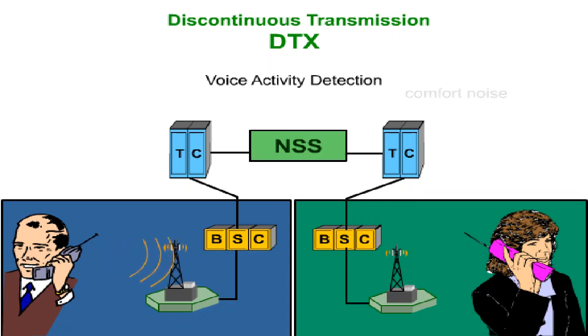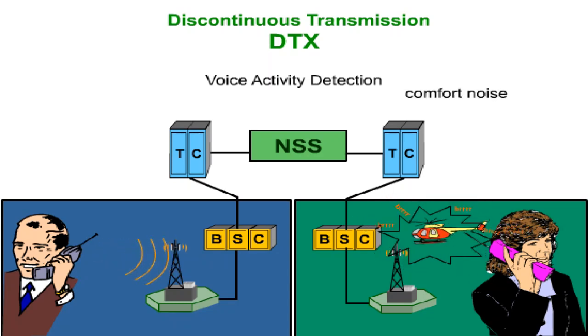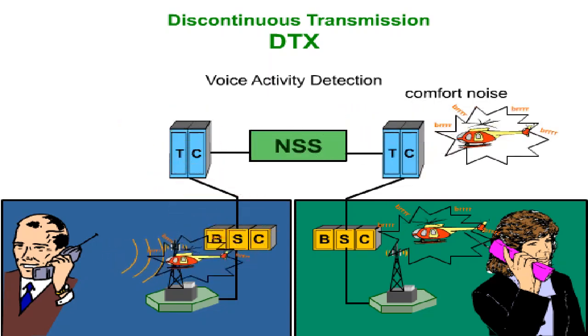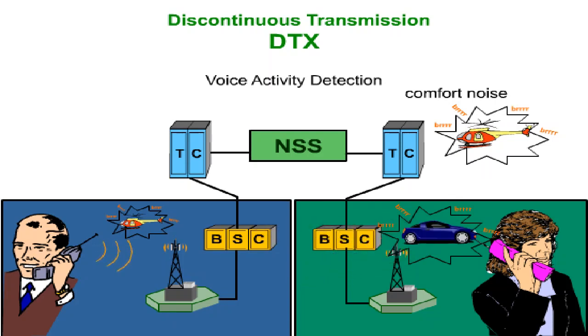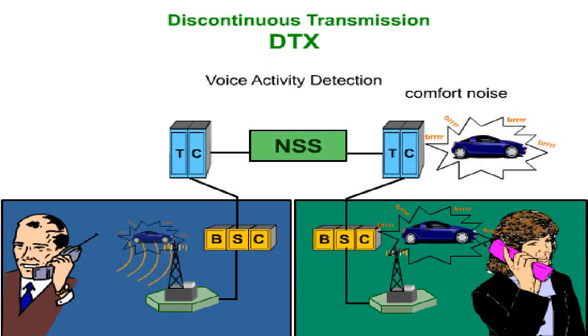In GSM, this is called comfort noise. It's the background noise analyzed before the MS is switched off, regenerated by the TC. The comfort noise is even updated during a speech pause by the mobile station transmitting relevant information to the TC.